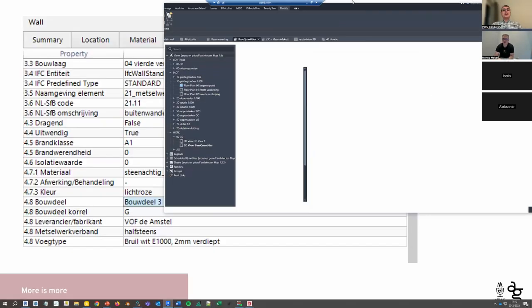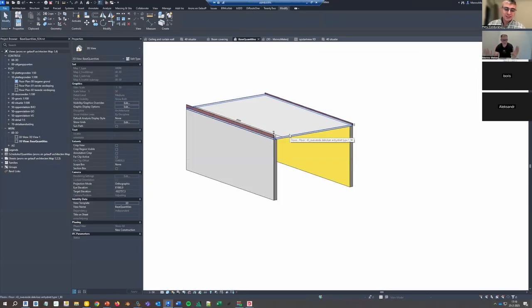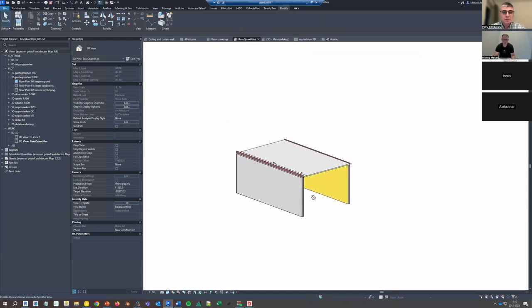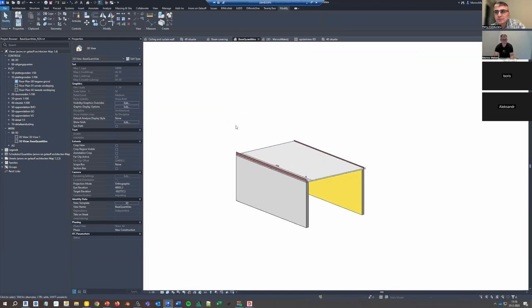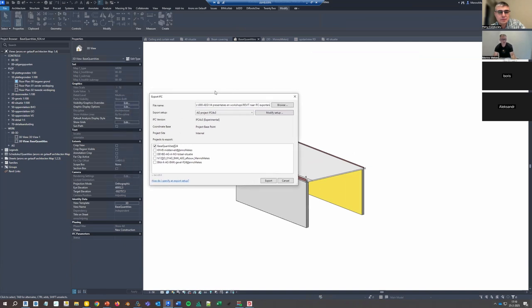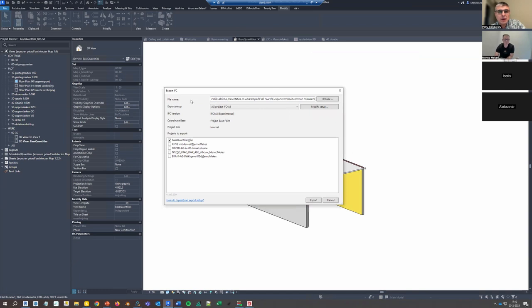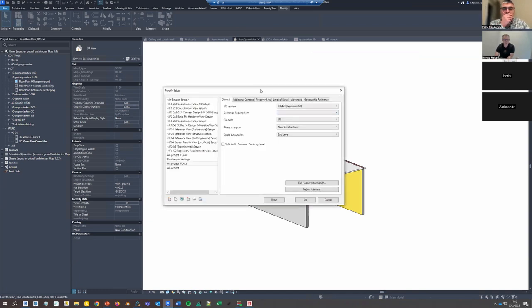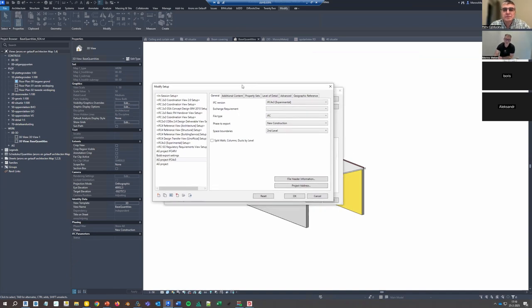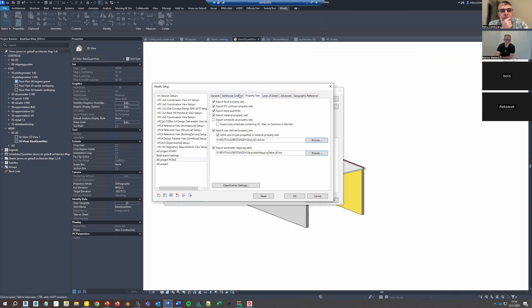Yeah, I don't want to hijack this and go into that discussion now. We can go from anywhere, because one of the things, I use a lot of shortcuts. So if you see something appear, this is the export to IFC. So we have one of the other common mistakes, I think, when exporting. We go to the tab called property sets. There are these property sets.